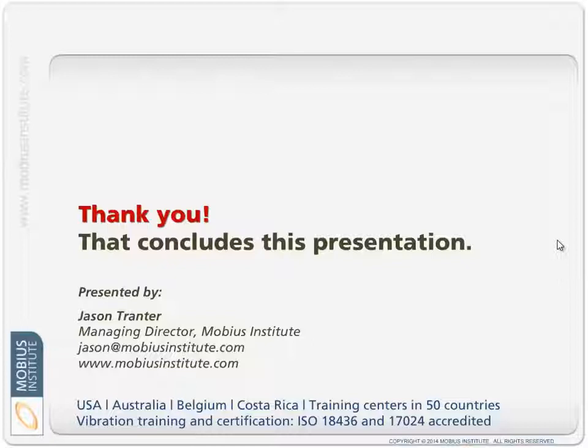It is really important that you understand how to take measurements properly, ranging from how you mount the sensor to how you set settings like resolution and Fmax, how you analyze the data, how you determine when phase analysis is important, time waveform analysis, spectrum analysis.